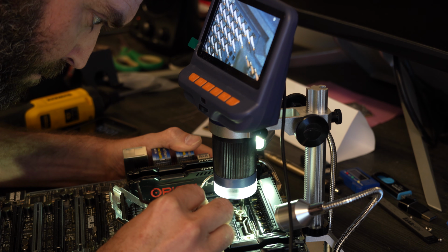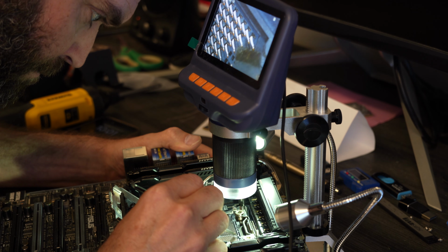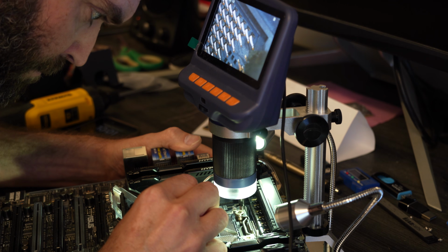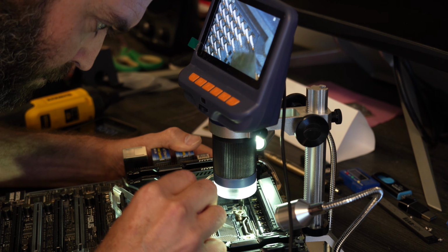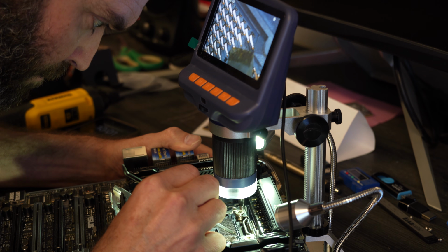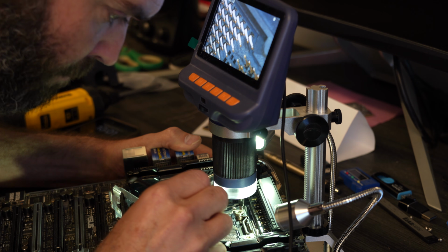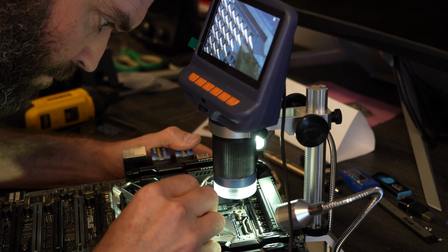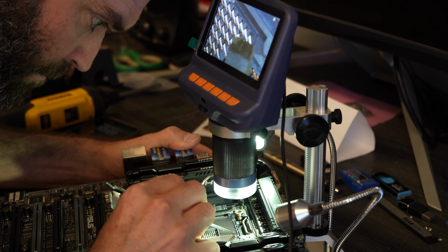I was really quite confident that I had narrowed it down to one of these 3 or 4 pins right here at this corner. That is the section that is the C channel according to the pin layout, and it didn't look bad. It was just off a touch. I tried several different ways to get this thing to boot, and I just ultimately had to use a new motherboard that came in just the other day. That's the MSI Z690, and just changed platforms. But I really wanted this to work on the X99.